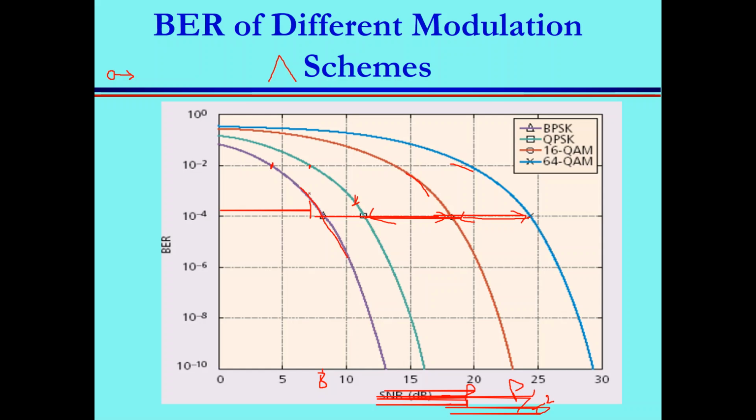So why don't I increase the speed of my internet by increasing the data rate and moving to higher order modulation? So when you reach this threshold, you stop using BPSK and switch to this curve. Why? Because now I can get 10 to minus 2, which is the requirement of voice communication, while also enjoying higher speed. Higher speed because QPSK is faster, it gives more bits per symbol. You keep moving, the user keeps moving. Here, the user switched to QPSK. Here QPSK, here it was BPSK, and the user keeps moving toward the base station. At this point, where the signal to noise ratio becomes 14 or 13, I can now use 16 QAM. Jumps again to the 16 QAM curve. Got it? This is the adaptation with respect to large scale fading.